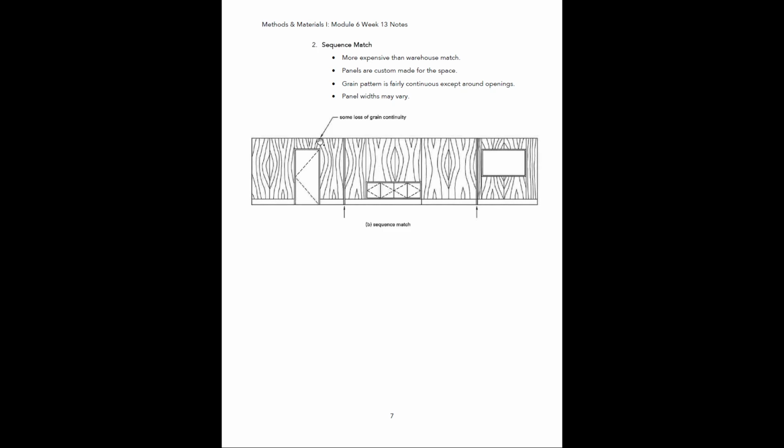But then whenever you're hitting these openings like doors and windows, you're going to have seams there, and that is going to cause some lack of consistency between the grain pattern. And also the panel widths in this method may vary.